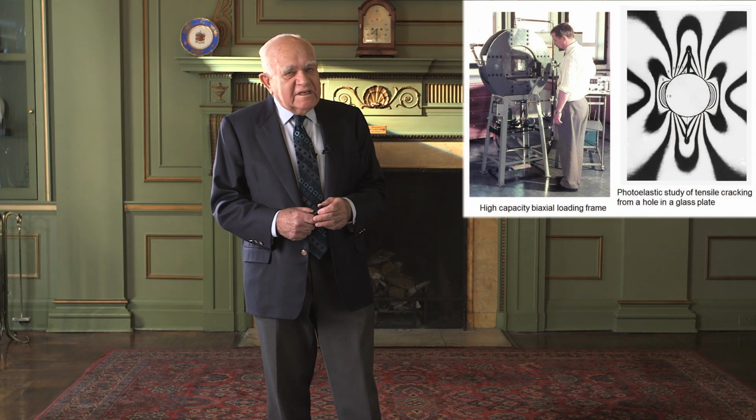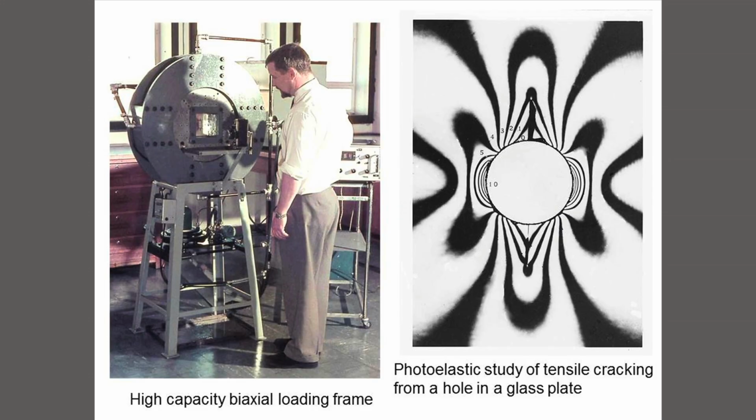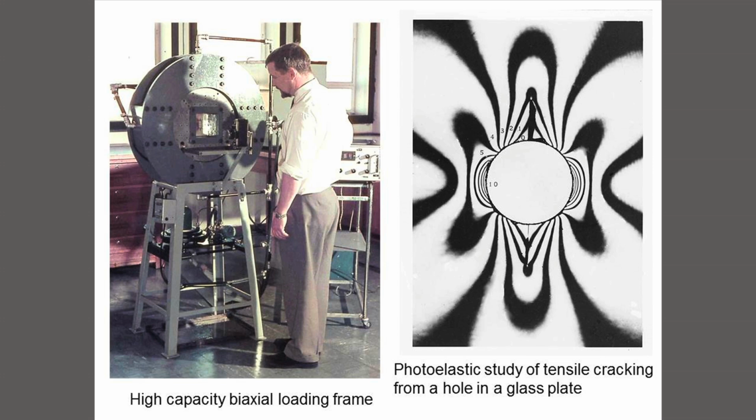But this is a very precise tool, and this slide illustrates a high-capacity frame in which we're able to load glass plates of about 15 centimeters square under very high loading, and by ultrasonically drilling cavities into the glass plates, you could study the behavior of cracks or tunnels or whatever you were interested in. And on the right there you see a photoelastic pattern showing stress distribution around a circular hole, and you'll notice that there are vertical cracks in the top and bottom, in the roof and floor of that simulated tunnel.